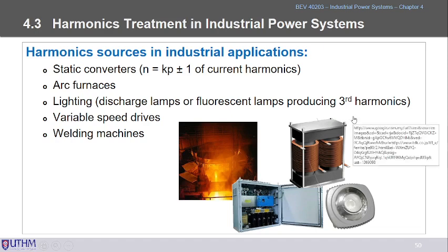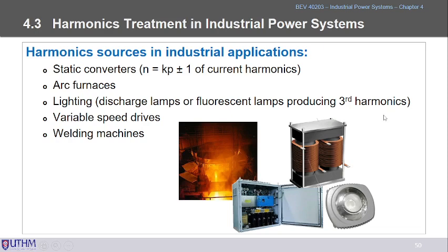When you have a little third order harmonic current content in the neutral, the RCCB will detect a difference between live and neutral, because in the healthy condition, live will return through the neutral, so live is always equal to neutral. In that case, the RCCB might trip due to the difference between the live and neutral contents. So that is one of the disadvantages of harmonics. It will disturb the protective devices.